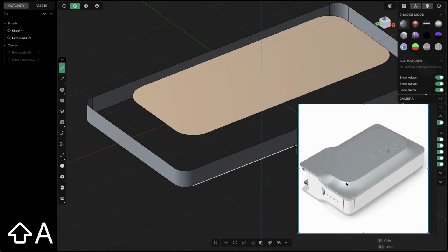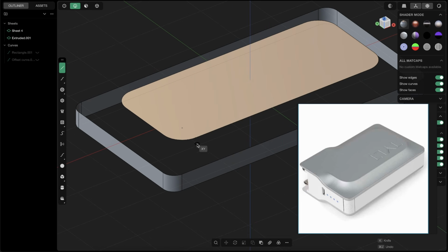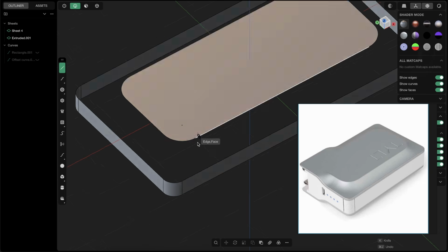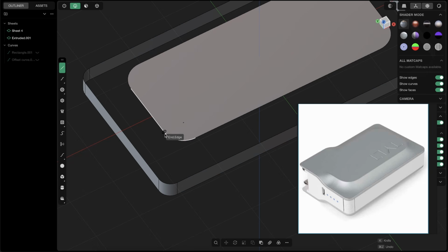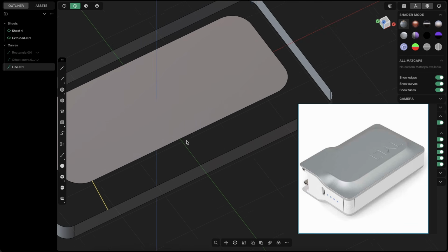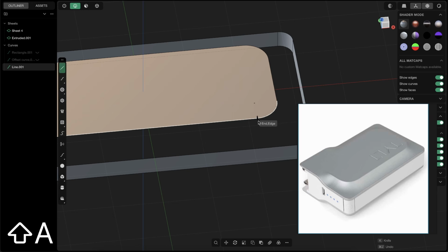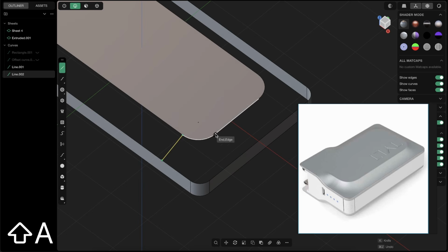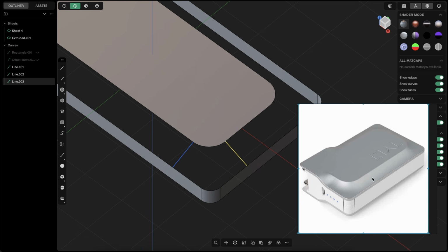And let's first of all create some straight curves. And here we have already this edge broken down because of the fillet. So we can just create a curve here and just snap it here to the closest point, right click. And now let's do it here as well, like that. And let's go here. So I'm basically just preparing first some curves.